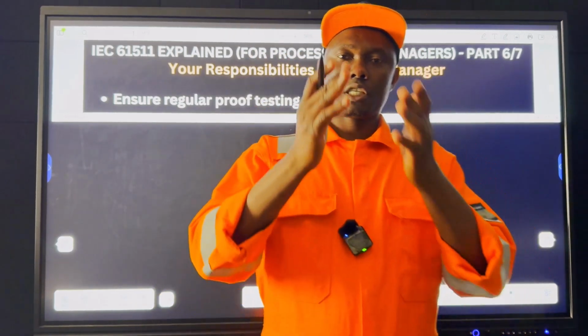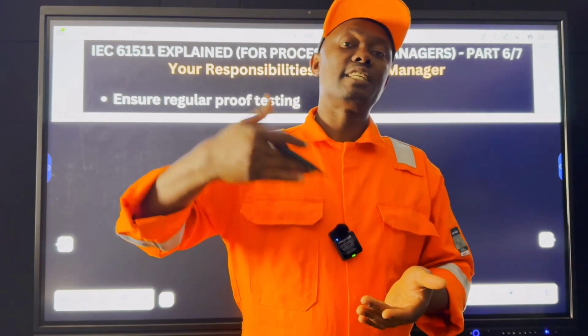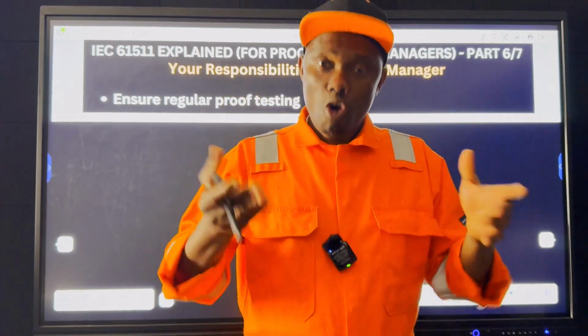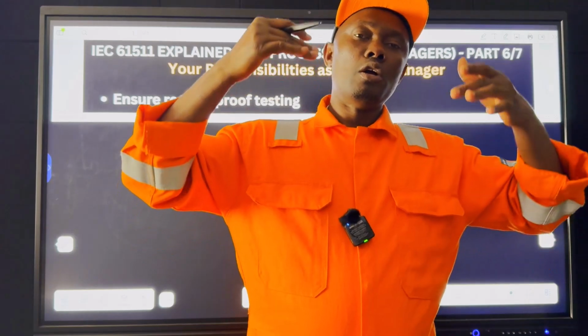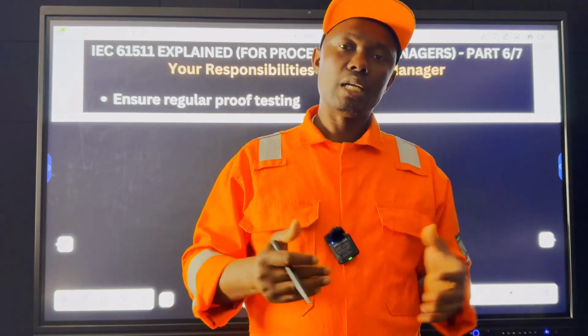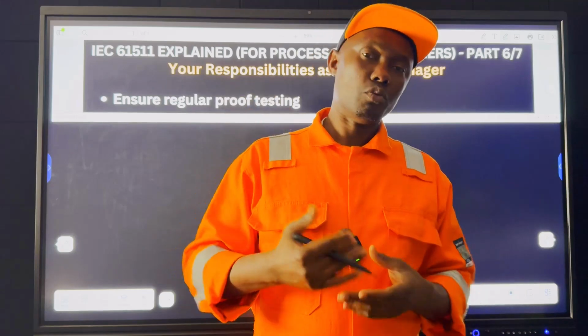So, if you don't keep to the documented interval, especially if it increases, it means you are increasing the probability of failure on demand, the unavailability of your safe loop, meaning you are increasing the probability that your personnel will be fatally affected if anything happens, because the possibility of a hazardous event occurring will increase.